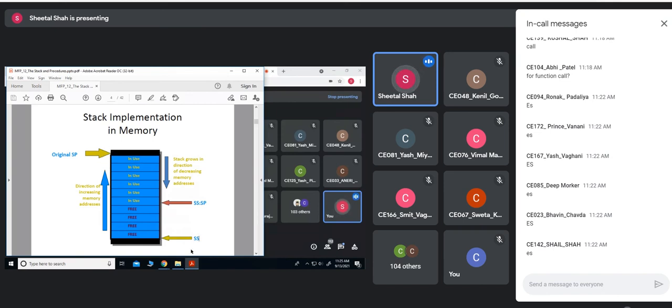Are you getting this? Say suppose this is my 0th address and this is my 99th address, if I'm talking about decimal addresses. So the stack pointer would be at the top of the stack, that is at the 100th address. Have you understood now? When we put some data onto the stack, the stack pointer value would be decremented. Getting all of you?